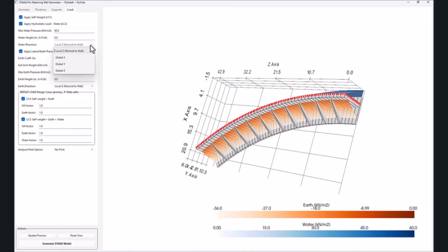Now, the important part is since this is a non-linear problem due to the compression on the spring, we cannot simply use the conventional load combination. Instead, we use the repeat load feature. This repeat load feature creates a primary load case in which different load effects are combined and solved together. This is very important because the nonlinear response cannot be obtained simply by algebraically adding the responses from the individual primary load cases. These are the default load factors. You can change them as per your need.